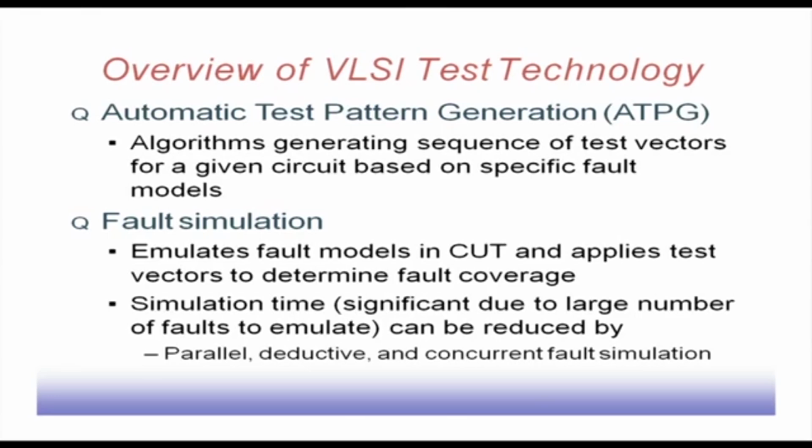Second, another important piece of software. ATPG is a piece of software which generates the test patterns. Another important piece of software needed by the testing community is the fault simulation technique. I am given a set of test patterns. Now, how do I know how many of the faults are actually covered by this test pattern set? For that purpose I need to inject those faults into the circuit, apply the test pattern set and see whether it is detecting the faults or not.